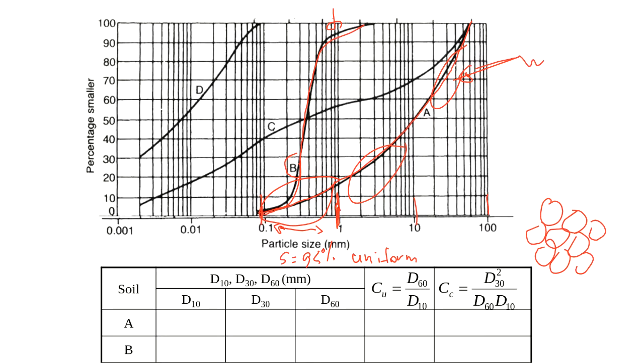Sometimes when you deal with sand, like beach sand, you can see that the sand particles are all about the same size. In this case, you can say this is probably poorly graded, uniform soil. Sometimes you see bigger particles of sand and gravel mixed with medium and small sizes, and you can probably have some idea that it is going to be well graded.